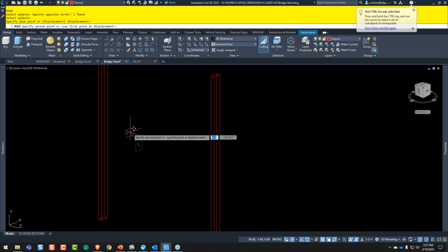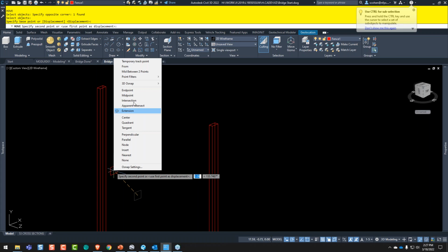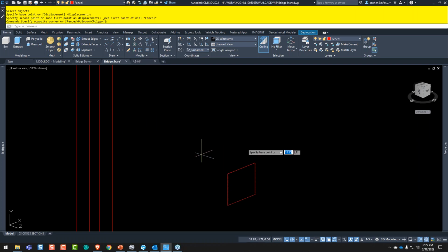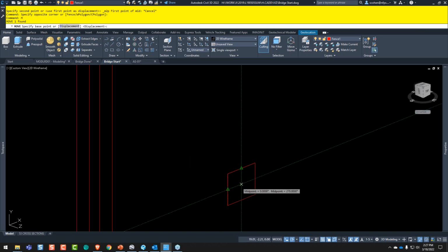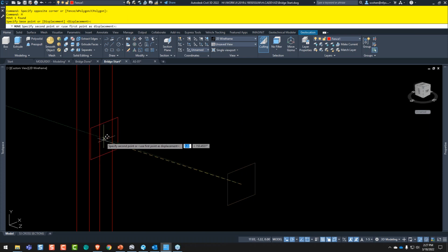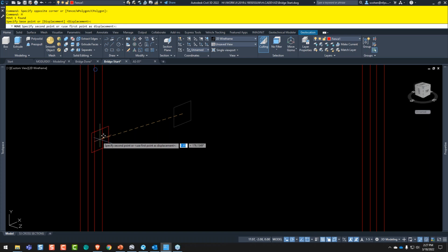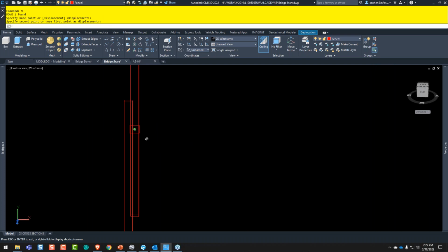There's that. And then now I'll grab the mid between 2 points. And actually, I take that back. I'm just going to go ahead and use that right there. I forgot about that snap, right? So if I move this, and we'll just track here, and acquire, and click. I like to show this one here. If you hover over a 3D solid, you'll see right there, see that circular thing? If I click, it puts it right on the face of it.